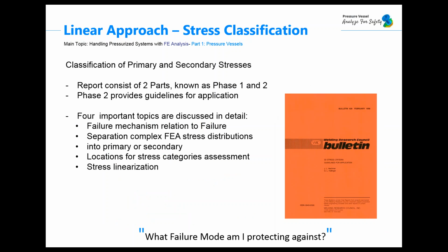So in other cases, for, let's say, stress classification, actually there are many challenges in regard to this process. All the time we have to ask ourselves where to put the valid stress classification lines. The next question is how to properly classify the stresses, how to properly classify primary, secondary, membrane, bending. And what if the linearized stress result is ambiguous?